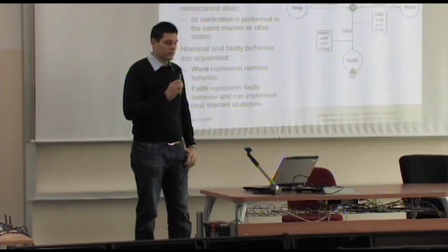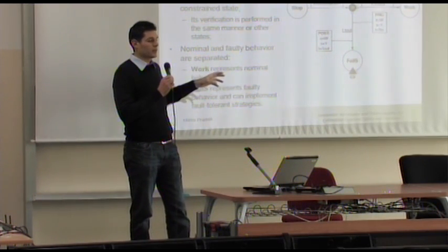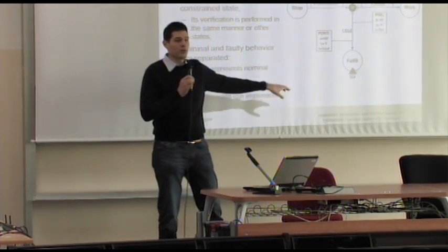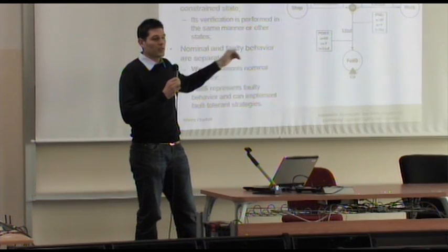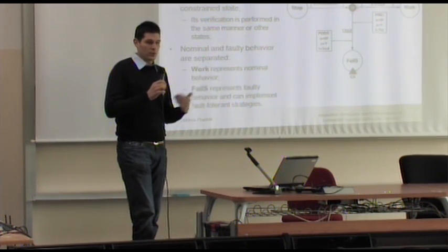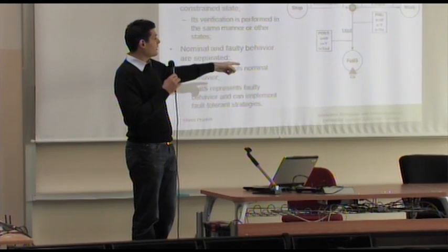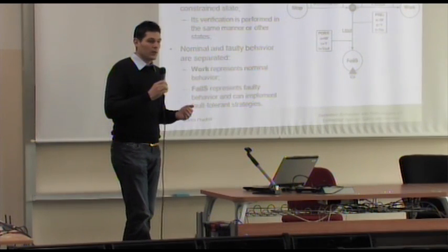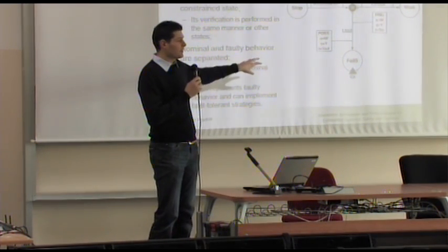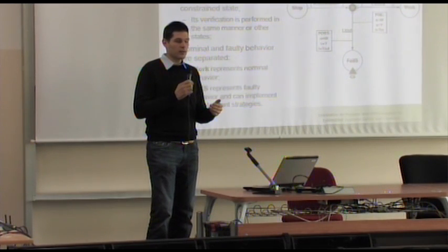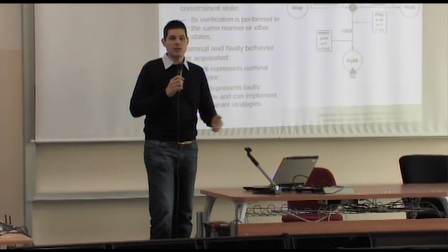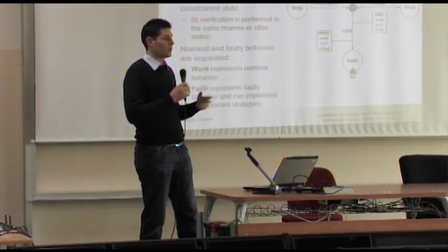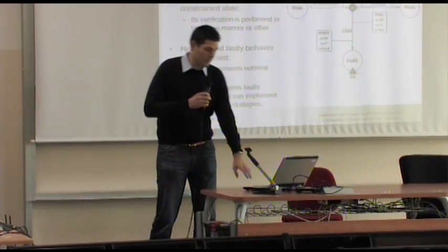Another important aspect of this pattern is that it allows us to distinguish the two kinds of behavior. The work state represents the nominal behavior in which the actuator is working correctly, but the fail state represents the condition in which the component has failed. So, starting from the fail state, we can implement the fault-tolerant strategies that the application requires. The two behaviors are formally distinguished and easily identified by this pattern.